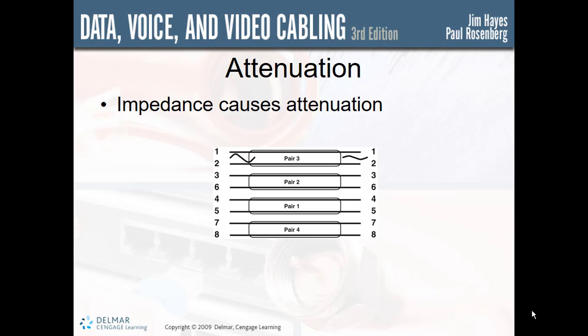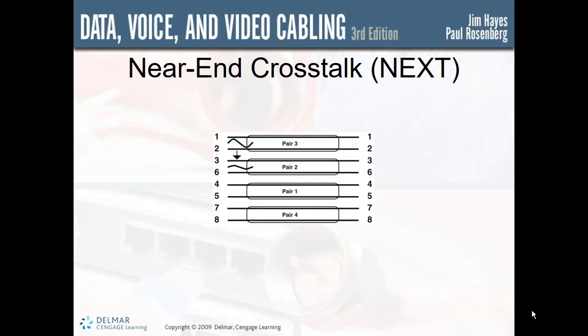Up to 60 MHz for Cat3, which is hardly used in our industry anymore except for telephones, 100 MHz for Cat5e, and 250 MHz for Cat6, and even higher for 6A and 7. Measuring attenuation requires an instrument at each end of the cable, one to transmit a known value, and one at the far end to measure the signal level and calculate the attenuation. Pass-fail criteria are set by the 568 standard. In short, the easiest definition that I try to give: attenuation is the weakening of the signal over time and distance.